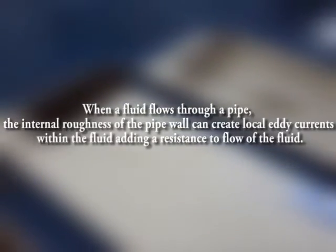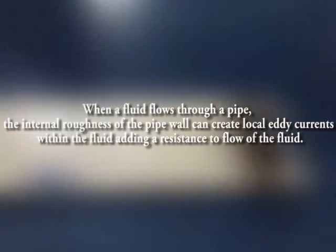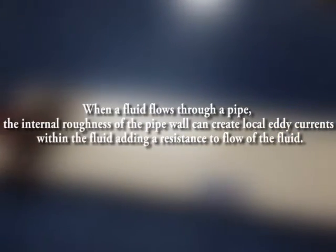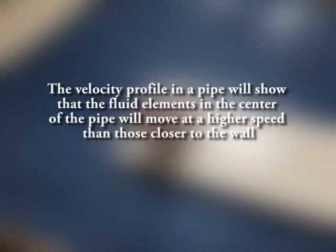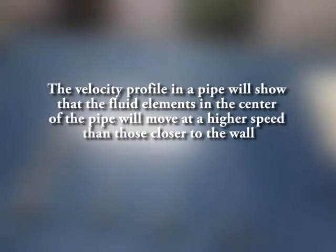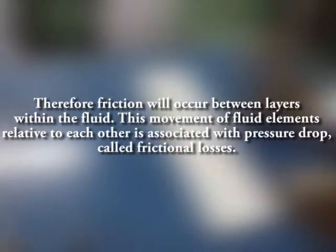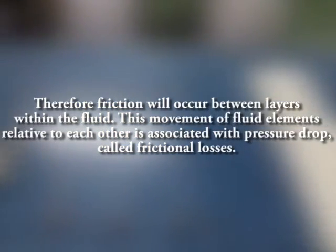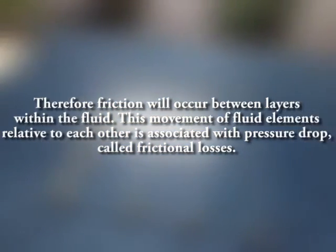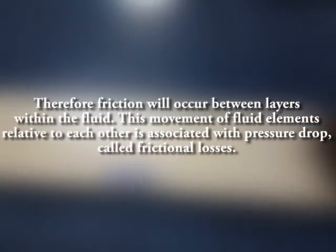When a fluid flows through a pipe, the internal roughness of the pipe wall can create local eddy currents within the fluid, adding a resistance to flow of the fluid. The velocity profile in a pipe will show that the fluid elements in the center of the pipe will move at a higher speed than those closer to the wall. Therefore, friction will occur between layers within the fluid. This movement of fluid elements relative to each other is associated with the pressure drop, called frictional losses.